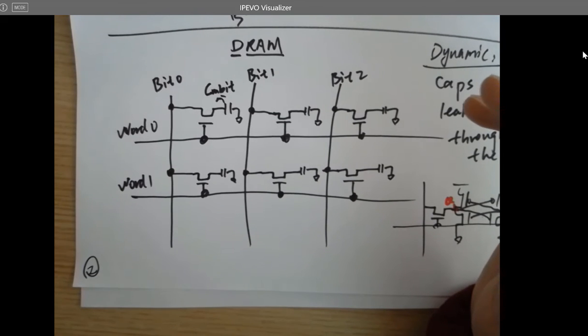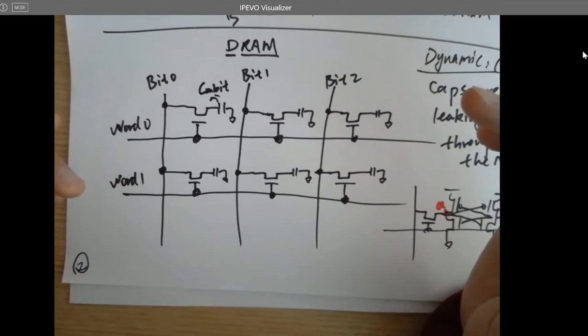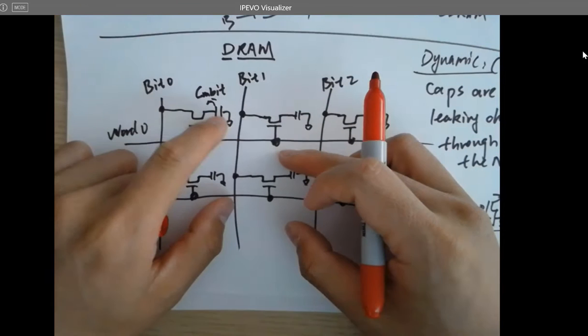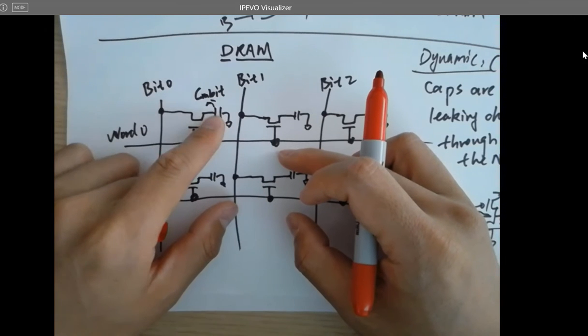It sounds better, right? Because you have larger memory, so you can run more programs. So in that case, we want to integrate more memory cells, and you have laid out one capacitor in one of the homework assignments. You know caps are taking space, so you don't want to make the cap too large.